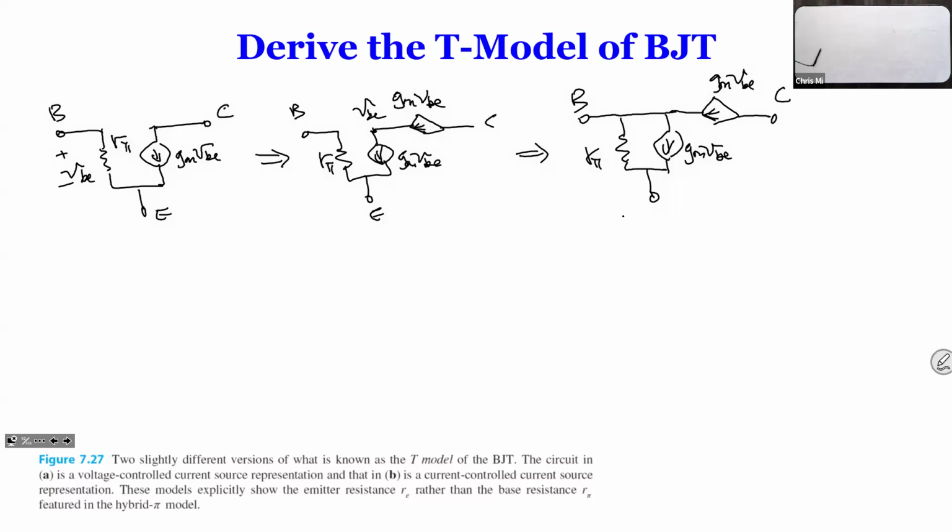Yeah, you have a good example. You have a 1.5 volts and you got 9 volts. You can have them in parallel. What happens? The 9 volts is going to charge that 1.5 volts with a huge amount of current because the internal resistance is very small. So now you're going to catch fire. Yeah, it's going to explode. It's a little weirder with current sources.